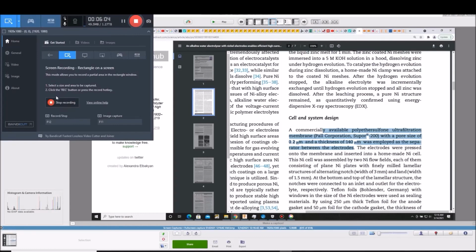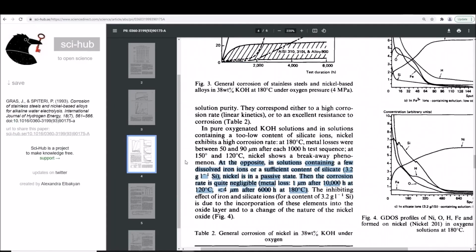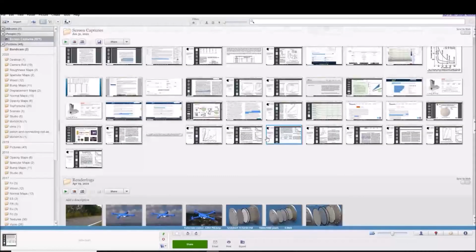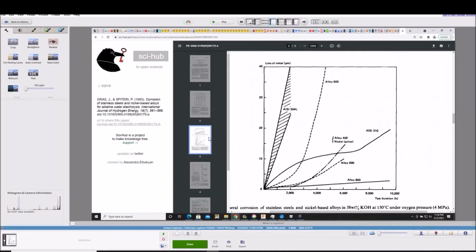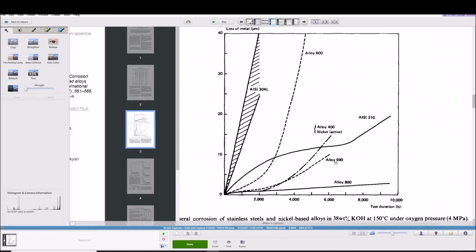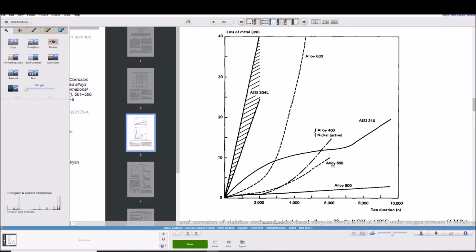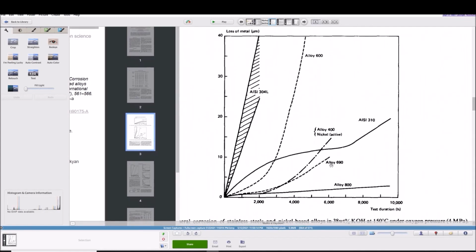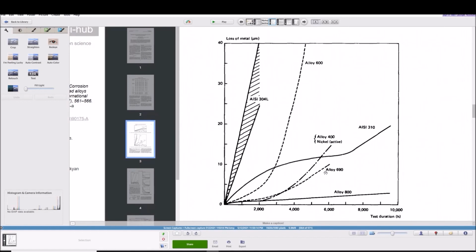So something quite interesting happens with the kinetics of nickel corrosion. What you find is that pure nickel actually corrodes at a higher rate than chromium ferrous alloys of nickel. So for alloy 800, which you can see here, it's about 30% nickel, I think about 20% chromium, the balance iron.